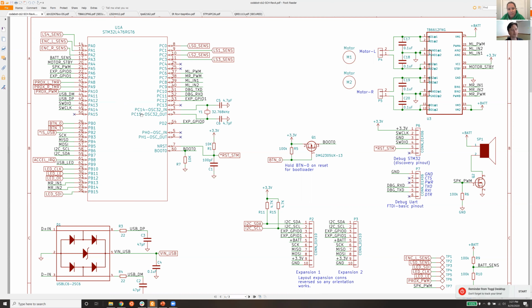There are few vendors that support it, but that's how our CodeBot firmware uploader works. If you ever have to put brand new firmware on, which is rare, but when we launch new features, we'll put out a new firmware image, and it completely replaces what's on that STM32. So there is no bit of software that can't be replaced by using that DFU firmware updater, which is kind of a cool thing from an engineering standpoint.